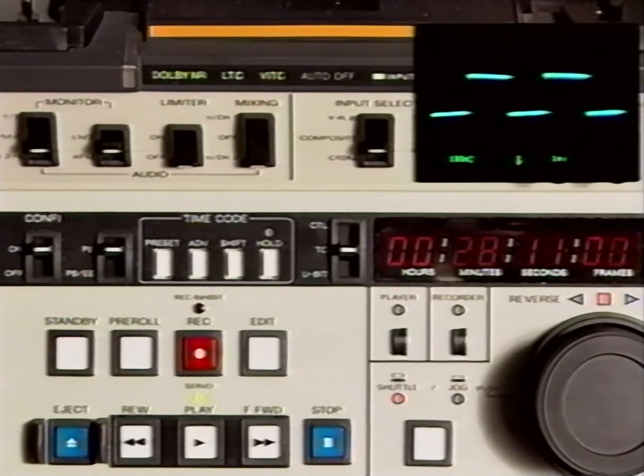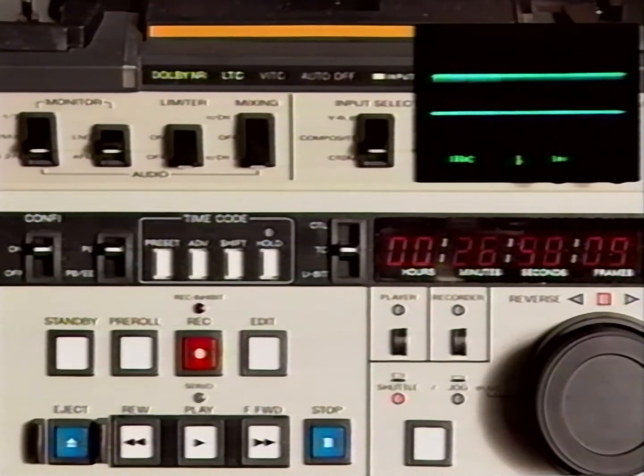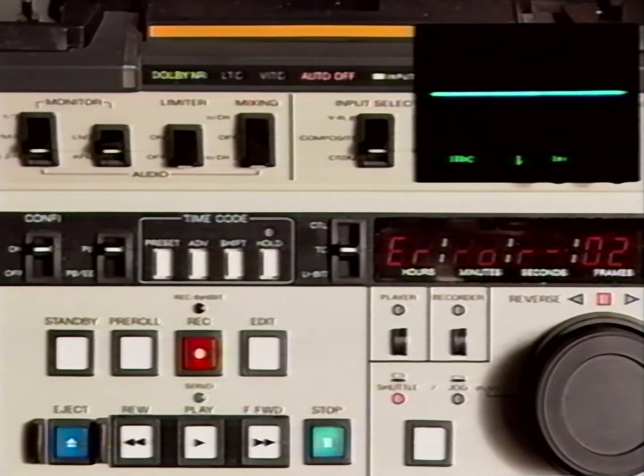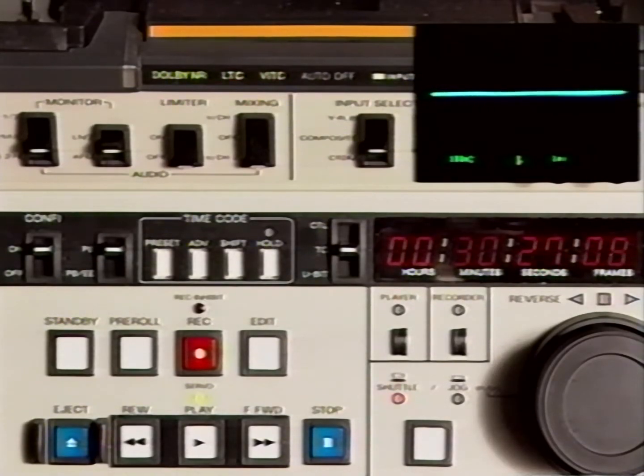When we misadjust the FG duty cycle and put the unit into rewind, the unit goes into auto off with an error 2 displayed on the counter. Another symptom of a misadjusted reel FG duty cycle is a rewind speed considerably less than 24 times play speed. When we misadjust the FG duty cycle signal in play, the unit goes to auto off with an error 3. The error 3 indicates a tape tension of less than 15 grams. The first 5 error codes are concerned with reel problems.